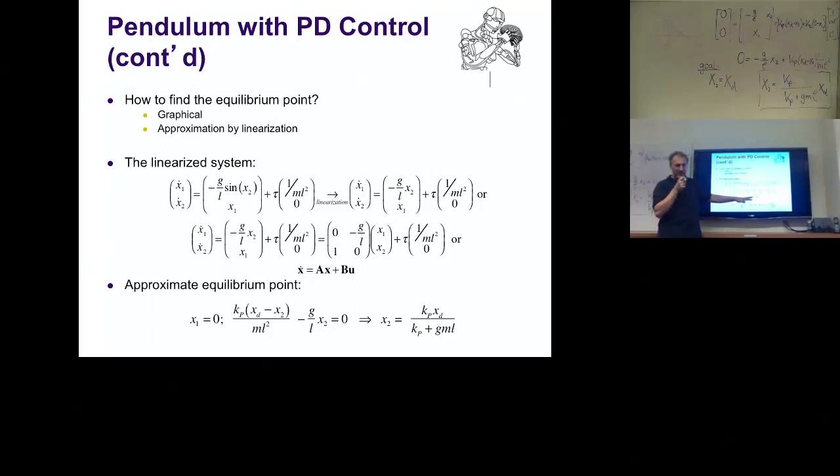But for the moment, we can just learn that by increasing the proportional gain, we're basically reducing the error of the system from its desired and forcing it to where we want it, which in theory is a good concept, practically not quite feasible. So in the end, you will find out our KP gains cannot become too big, otherwise the system becomes unstable and literally explodes.